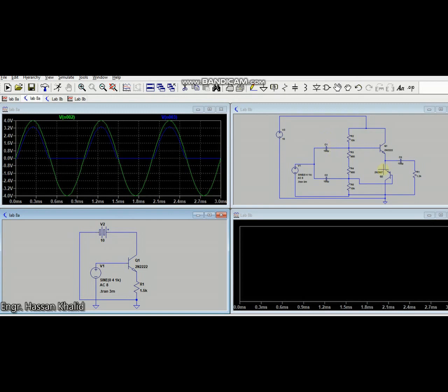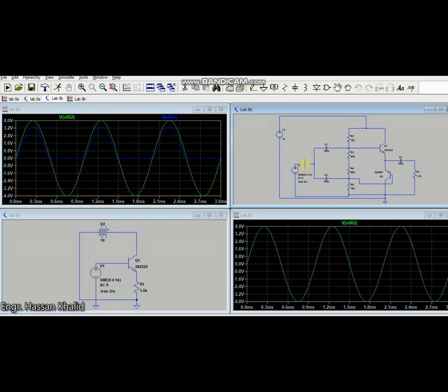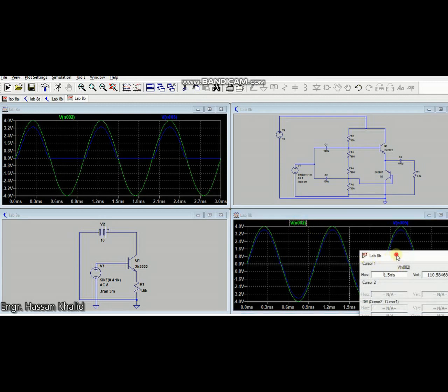Now this is our improved circuit that has the complementary sets of transistors in symmetric form, one is NPN, another one is PNP, and here once again we have this input, and this one is the output voltage across this resistor, that is 1.2 kilo ohm. Similarly, there was a difference of 0.7 volt over here, so let's check what the difference is right now.